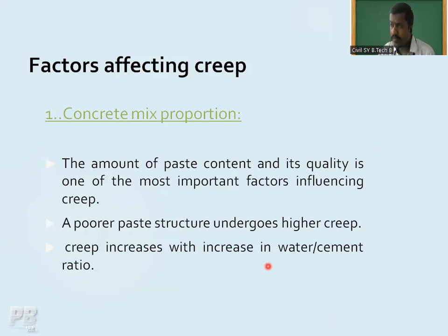As I told you, take the minimum water cement ratio as recommended in the Indian Standard code, or as you have designed it. If you are using admixtures, maybe plasticizer or super plasticizer, you can reduce the quantity of the water content by 20 to 30%. It depends on the type of admixture that you are using, because admixtures have different roles. So you can curtail the water to cement ratio.